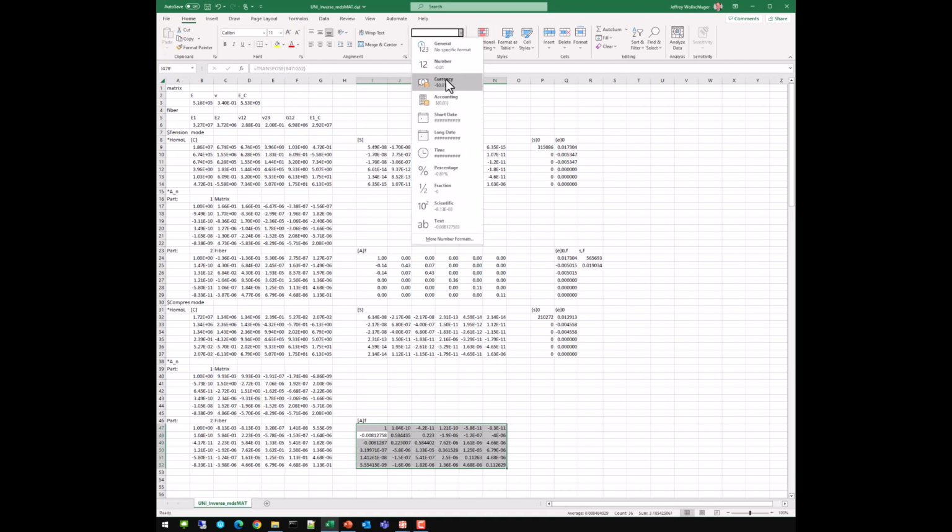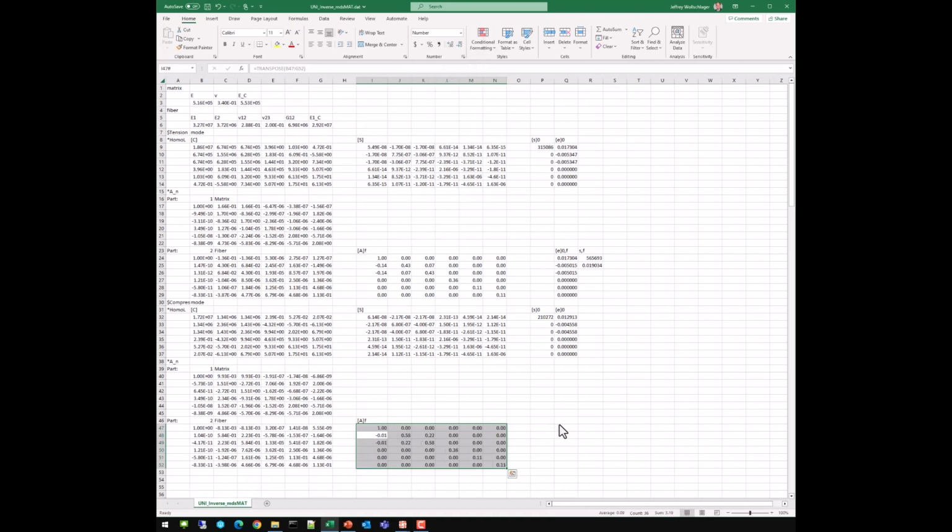Put that into something that's a little more human readable. And that allows me to calculate the strains of the 0 degree specimen in my fiber, which is nothing more than the multiplication of the amplification matrix times my homogenized strains. Great, all is good so far. I've got 1.3% give or take.